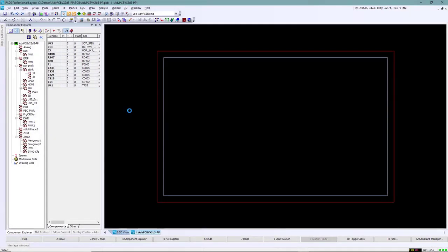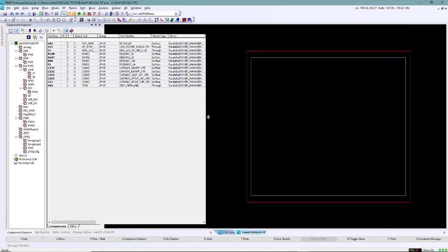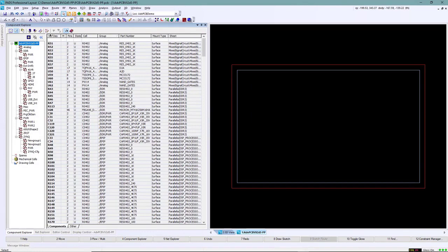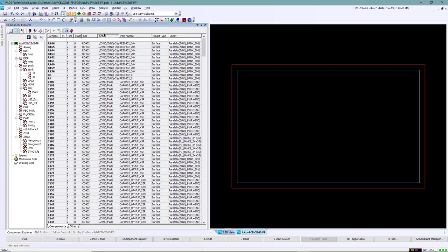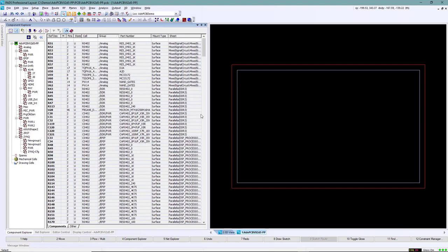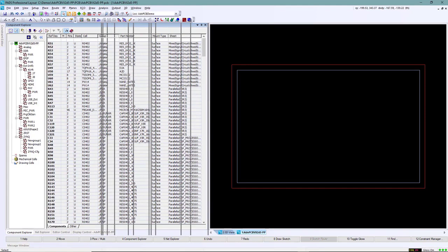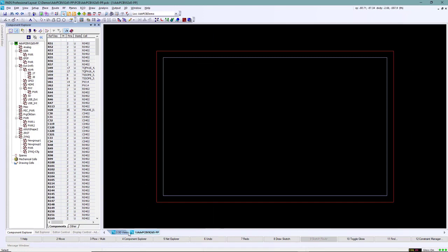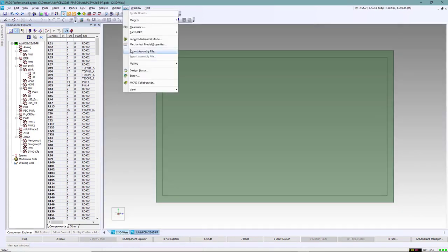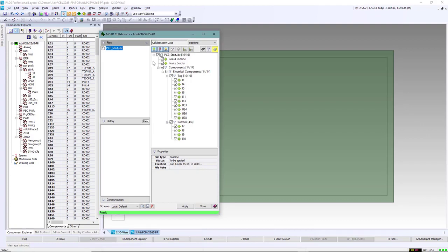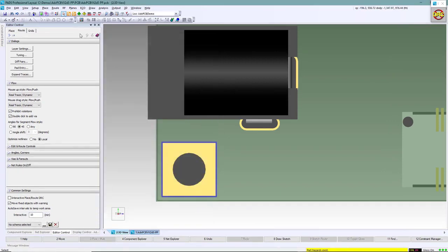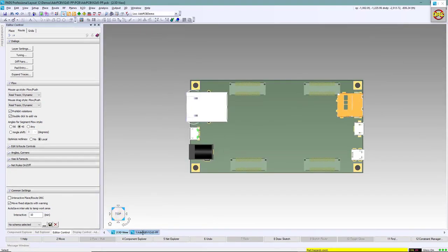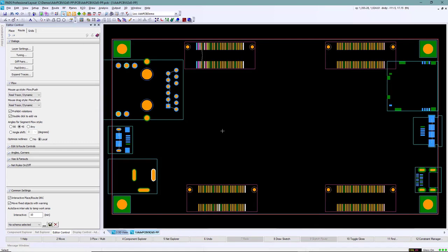Most designers start a PCB by grouping parts using cross-probing from the schematic. However, using a spreadsheet-based view like Component Explorer allows us to quickly see information about our components and groups created for each circuit. These groups can be created either in the schematic or PCB. We'll be starting this design using MCAD collaboration. As with most designs today, the I/O interconnect interfaces with a mechanical enclosure. As you can see, this dramatically reduces placement of mechanical critical components. Additionally, changes can be passed between each domain.